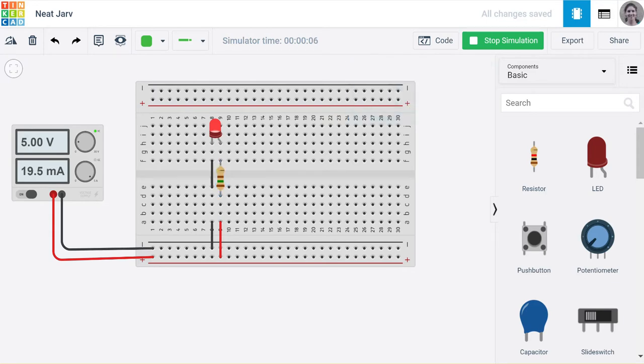150. I want to tell you something. The limits depend on the type of LED, and they depend on the color. So it's not the same limit for red, blue, green. For your RGB LED, that is a multiple color LED that you will use for the automaton, it will not be the same resistors for each leg. So don't try your RGB LED in your engineering kit before you do the activity in Tinkercad for the automaton.